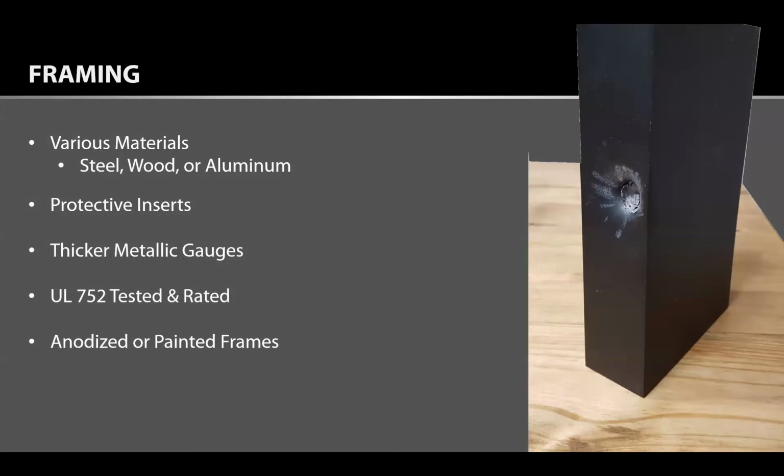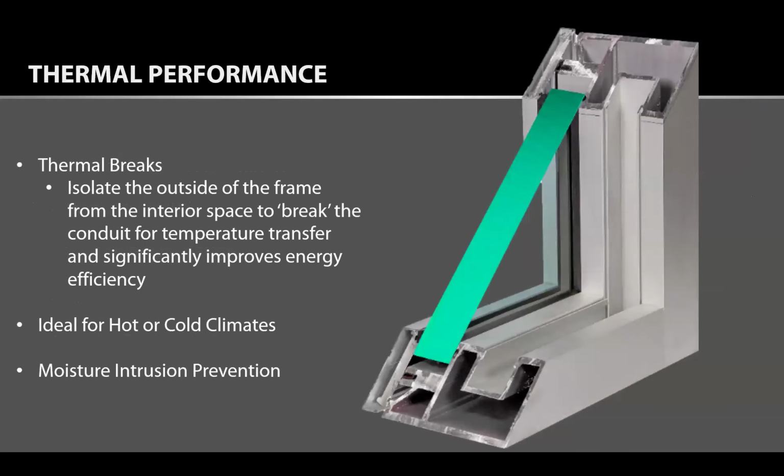I hate to say this, but hollow metal frames are not ballistic rated. Your standard anodized aluminum or hollow metal frame you're walking out of every single day will not meet the higher levels of ballistic protection. It will not meet storm impact requirements. It will not meet blast requirements, or in some cases, some of the higher levels of forced entry requirements as well. So just know that there are aluminum solutions out there that still give all the appeal and all the design creativity that you want for exterior envelopes while still offering security and thermal properties as well,